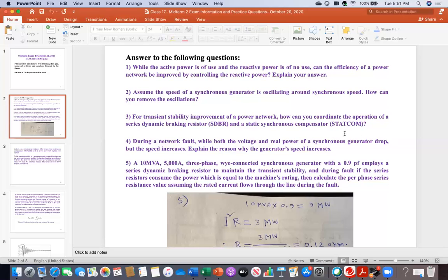The same thing happens, in fact, with all parallel connected devices: energy storage, SVC, synchronous condenser, any parallel capacitor, then the braking resistor. Everything actually comes into operation after circuit breaker opening, because the circuit breaker opening time is not big, maximum 5 cycles. Once the circuit breaker is open, there is enough voltage. You disconnected, you broke the current. That's why it is called a circuit breaker. But now there is voltage, and that voltage is enough to operate the STATCOM.